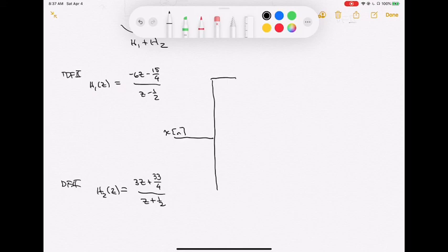The system on top is a DF2 structure, so I should get my zeros first, followed by the poles. This first one's going to come through some coefficients. These coefficients are going to get into these summing nodes. You could go back up in the lecture if you wanted to see this. Then we are going to get some particular output, but that output also gets fed back through another coefficient.